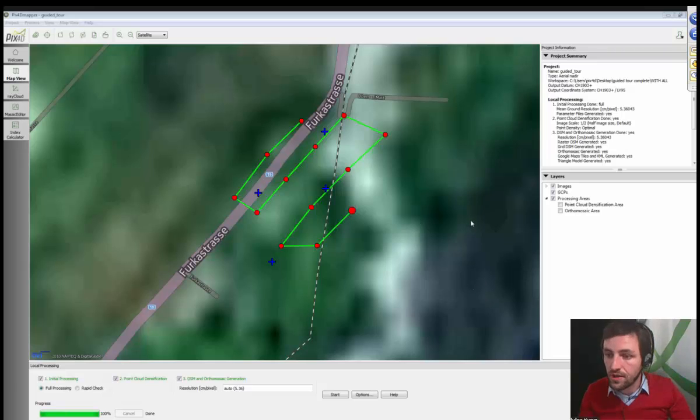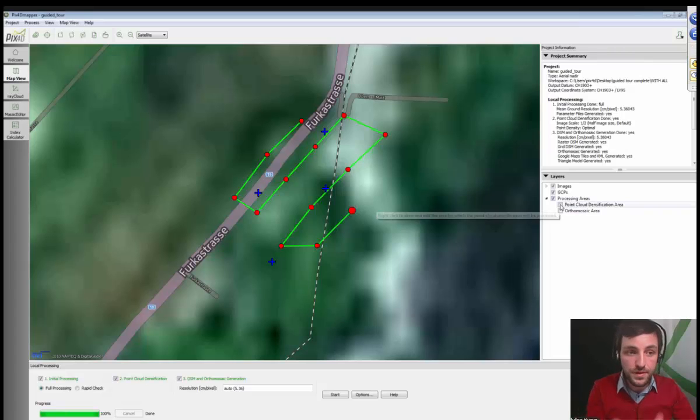So let me check the questions which are now asked by several users. A user asks if the geotags can be imported from EXIF. As I mentioned before, yes, it can be. The software is automatically going to read the geotag inside of the EXIF. Okay, so here we show the boundaries as a pre-processing step, but it's also possible to define these boundaries as a post-processing step once you have the final orthomosaic, which I'm going to show later on how to do.